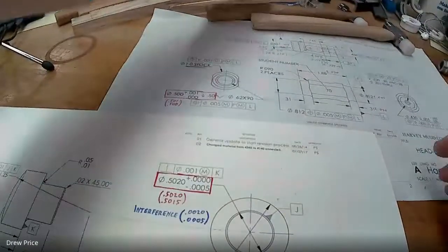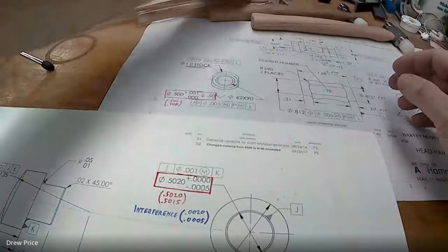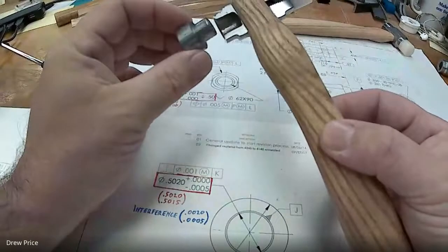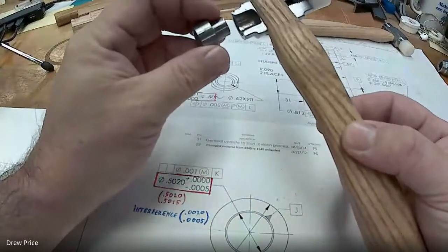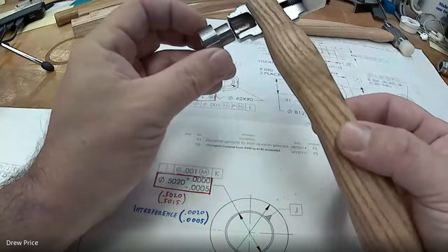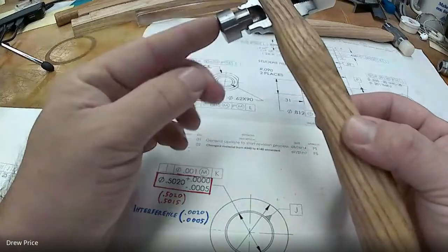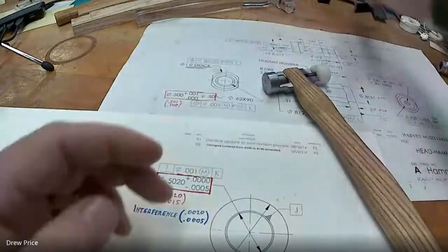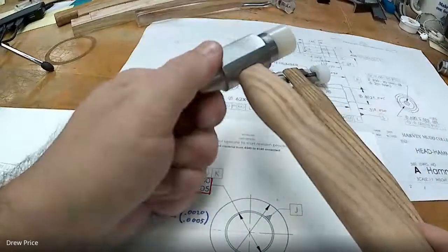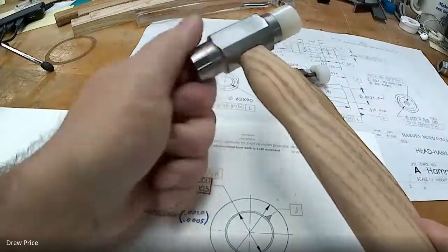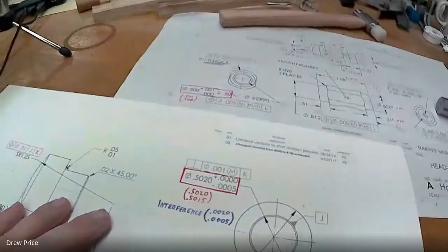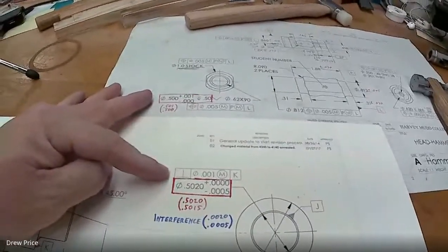And those two parts are where this portion of the head is supposed to get made so that this pin is larger than the hole that it goes into, and we have to actually force them together using a press tool in the shop so that they won't come apart. So in a complete one, when it's put together, this portion shouldn't be removable. It should be permanently attached. And the way that that's shown on the drawings are in these two red boxes.